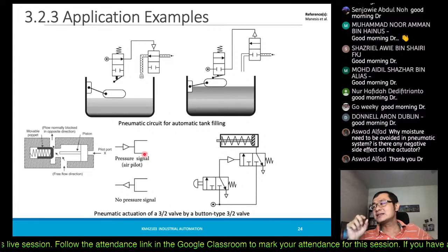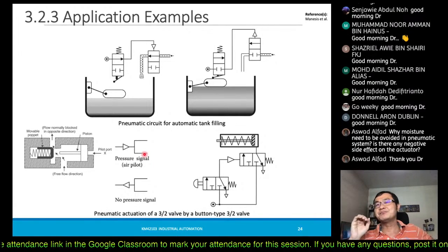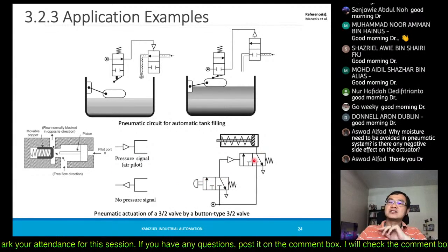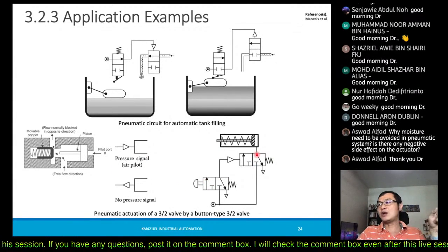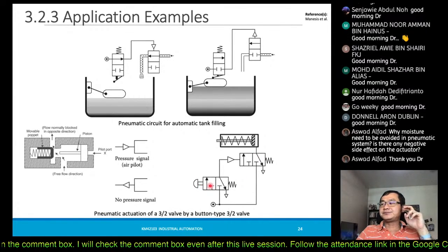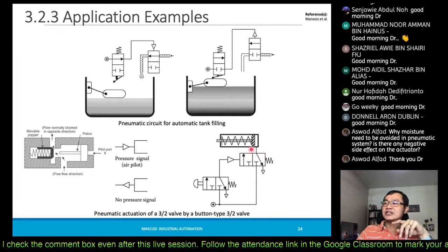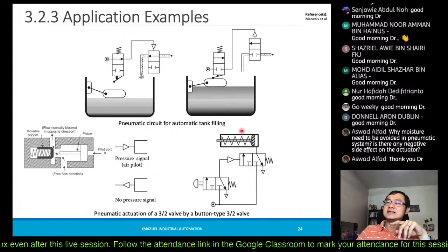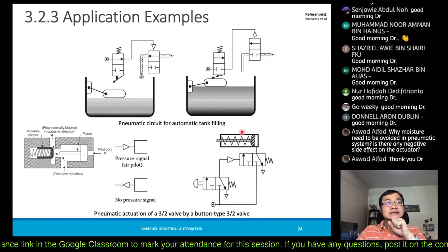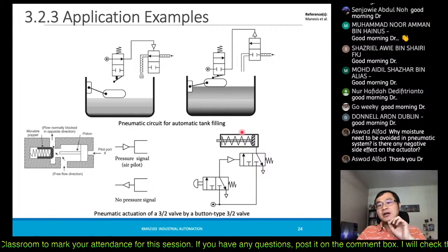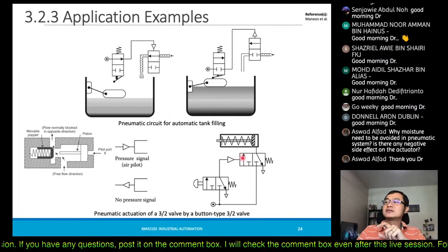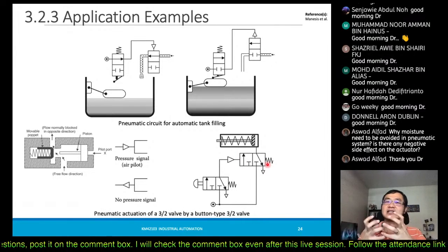The idea is that sometimes you may want to operate multiple cylinders. By pressing one, it can control multiple valves. Or this piston cylinder may have a different requirement of power or pressure, so the selection of the valve may be different. The sizing of the valve is different.